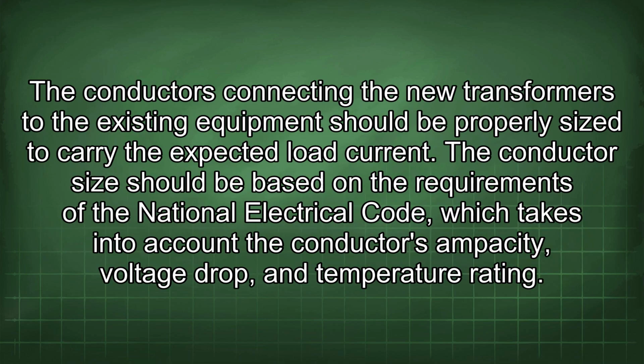The conductors connecting the new transformers to the existing equipment should be properly sized to carry the expected load current. The conductor size should be based on the requirements of the National Electrical Code, which takes into account the conductor's ampacity, voltage drop, and temperature rating.